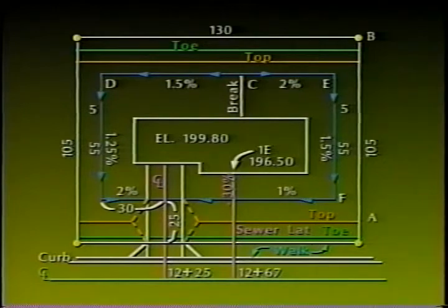Property corner stations can be calculated using the station on the driveway center line, the dimension given from the driveway center line to the west property line, and the width of the lot. The elevations can all be calculated using the street profile that is given. 2 of these elevations are in a vertical curve section, so you must be familiar with vertical curves to solve the problem.